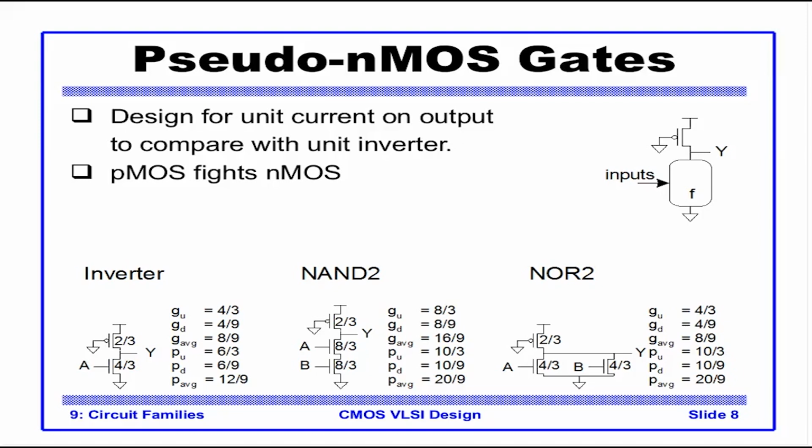Now let's consider the pull down case. What happens during pull down is what makes it different from a regular CMOS inverter. For the case of pull down, the PMOS and NMOS are both on. Now in this case, the capacitance seen by both input and output are reduced. In the earlier inverter, the CMOS inverter, A sees the cap of both NMOS and PMOS. But here A is just seeing the cap of NMOS. So now we say that in both G and P cases, the capacitance gets further divided by 3.